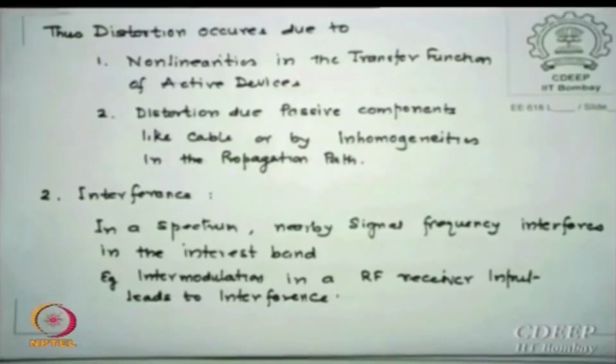The simplest intermodulation can be understood without even a receiver. You have two transmission lines or two signal lines. If they are close by, due to just mutual inductance coupling, the signal in one may couple to the signal in the other. This is called crosstalk. When is crosstalk highest? When the signals on the two lines are moving in opposite directions, the crosstalk is the peak of both, like differential. So that is the highest crosstalk.